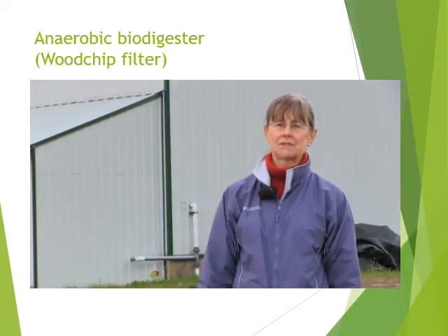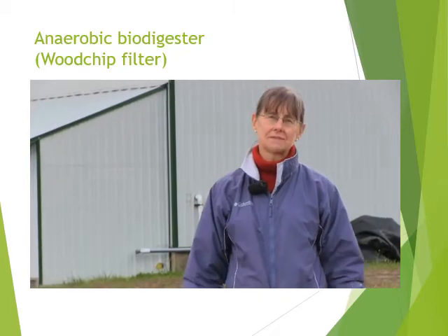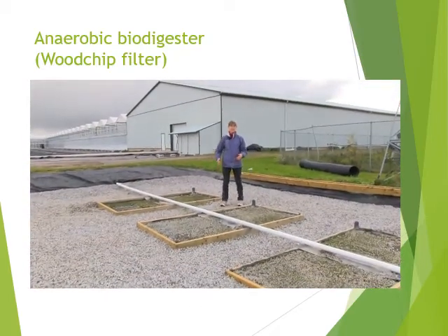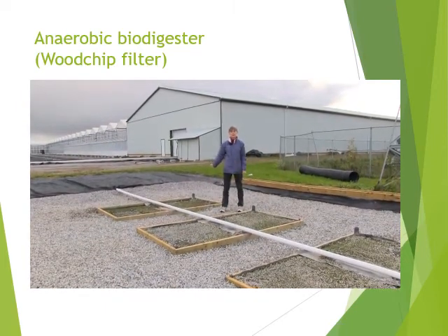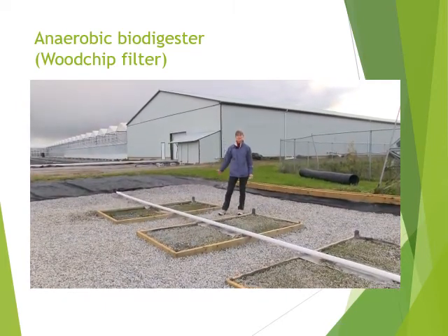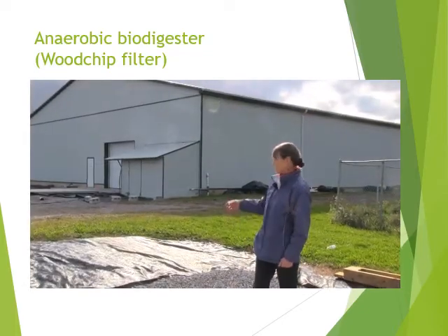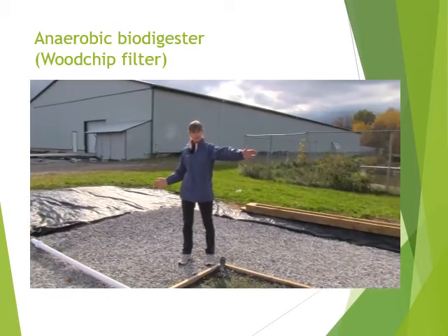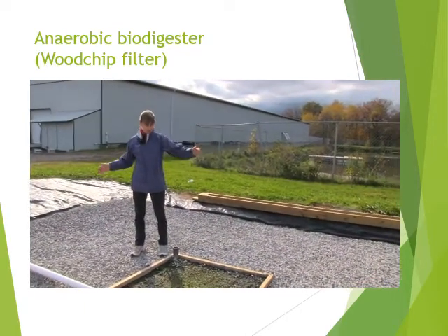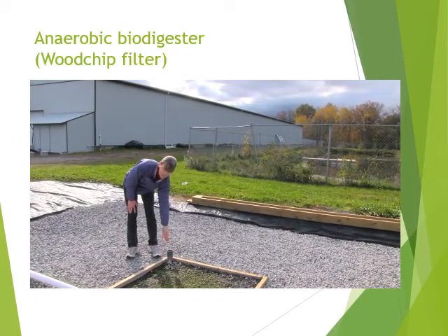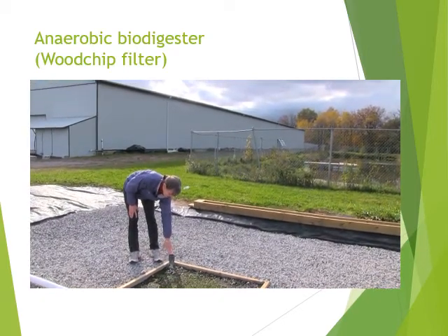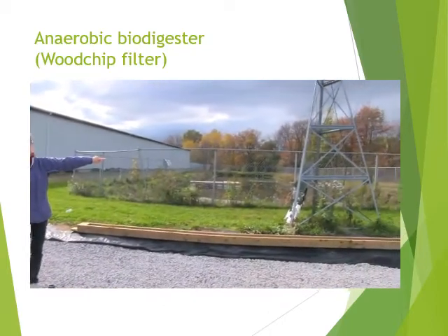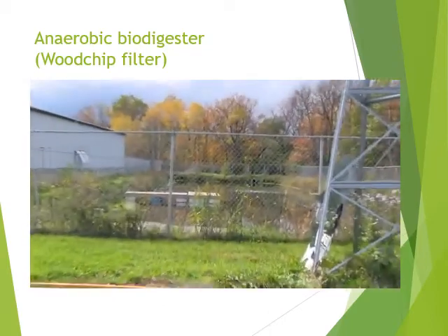For the RAMI project, we are also looking at how effective the system is at removing plant pathogens so that the grower can then reuse the water and recycle it back into his irrigation water system. For the project, we are sampling as the water comes out of the greenhouse, as it goes on to the denitrification biofilter, and as it comes out of the treatment system, we can sample here, and the end product then goes into the pond.